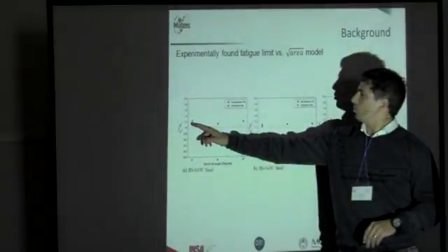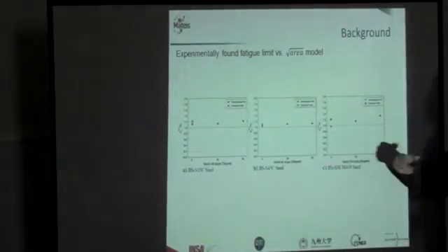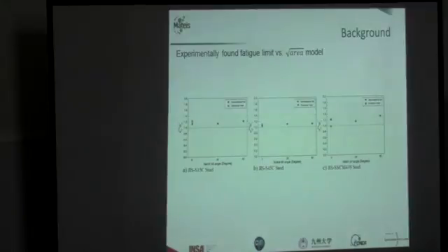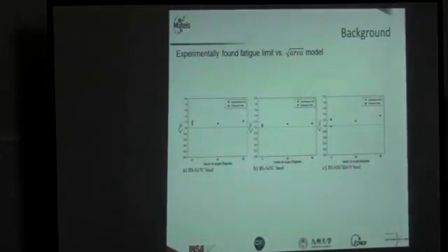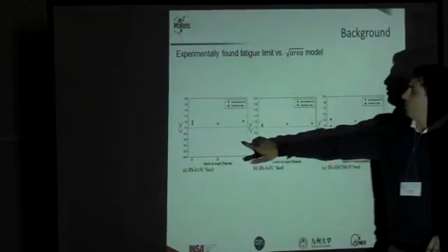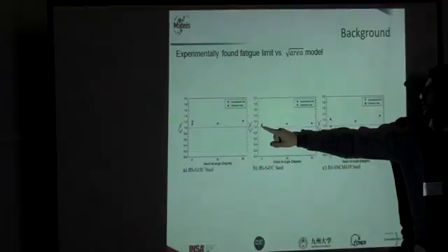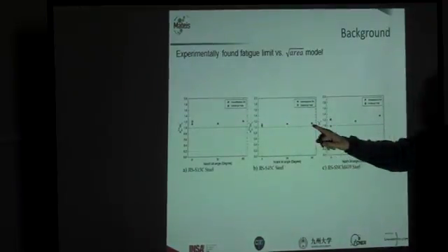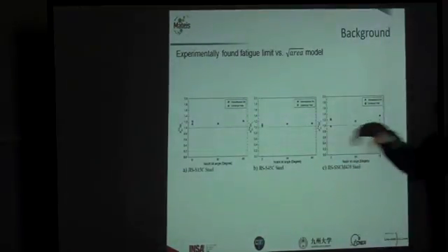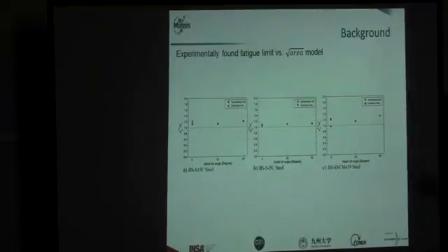And we observed no big influence of the tilting angle on the fatigue limit of these first two carbon steels. You can see again here that the fatigue limit is within 10% of the prediction of Murakami's model.